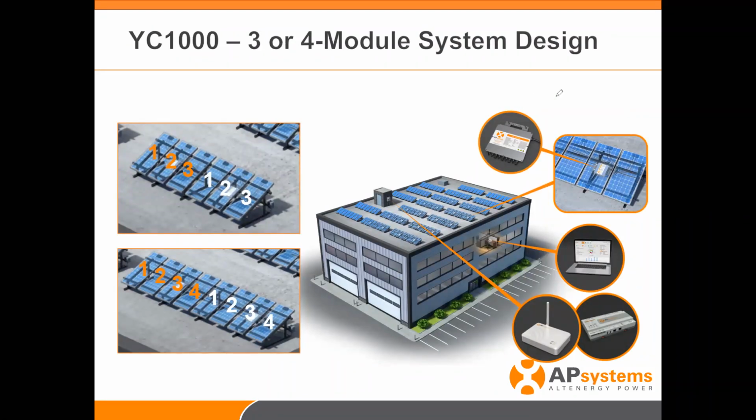We talked about this just a moment ago, talking about the 3 or 4 modules design. Basically, for an industrial, commercial environment, that really depends on what you're trying to do. If you have single row portrait, single row landscape, depending on module sizes, you might be able to put 4 together on a single inverter. If you can only do 3, let's say you have larger modules, say 400 watt modules, you may only use 3 of the ports on the 1000. So you'd actually utilize 1, 2, 3 in this 3-port design here. Then you'd just cap off the 4th channel using MC4 caps, watertight, dust tight, to seal it off.